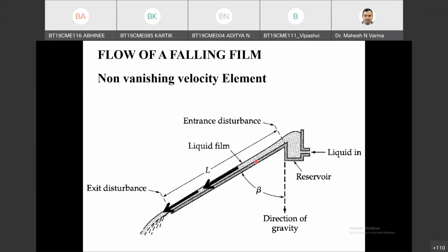So if you observe the geometry of the cyclone separator, the upper part is a cylinder and the lower part is a cone. Most of the time this cylindrical part can be solved by the cylindrical coordinate system, and if I have a conical shape of the boundaries, then it will be easily solved by the spherical coordinate system.